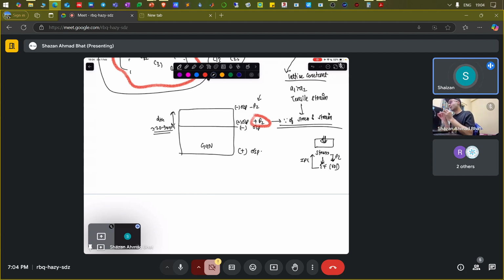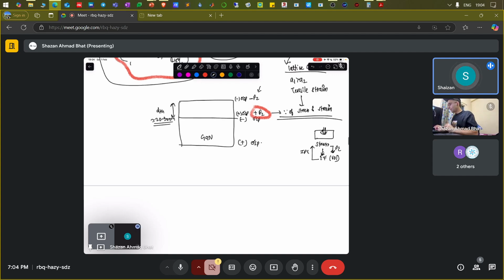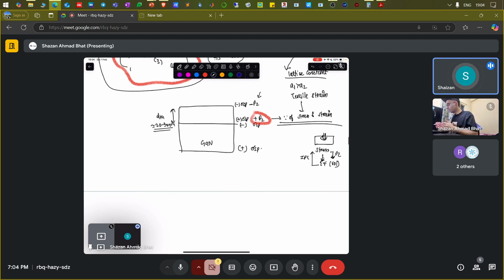That means stress has been developed because of lattice mismatch, and that gives rise to an electric field in such a way that the top becomes negatively charged and the bottom becomes positively charged. So it turns out that spontaneous polarization and the piezoelectric polarization play a huge role in the generation of the two-dimensional electron gas, or the electron channel, in these devices. Okay, and now you have to consider one more thing.